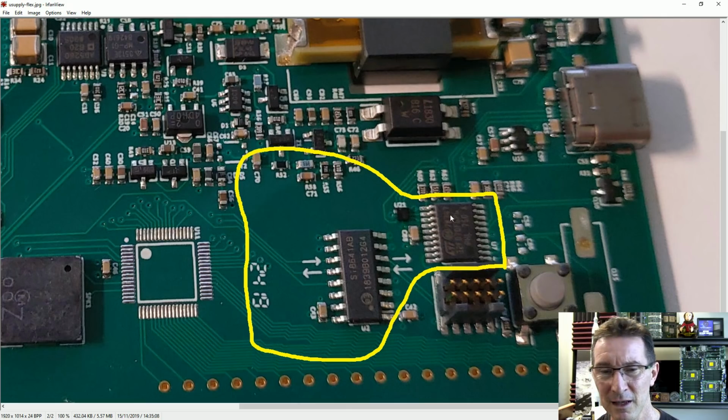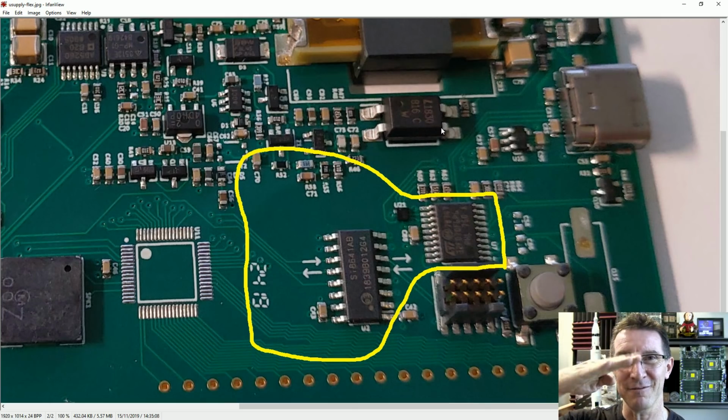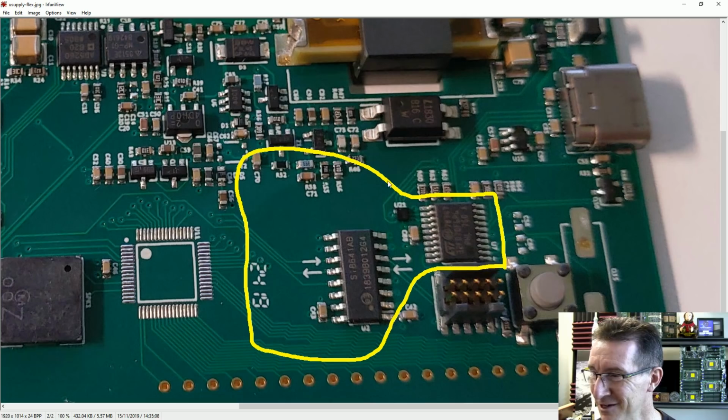So really, yeah, I think I'll just have it coming out like this, because there's a bit more gap between that chip and those pads than there is between these resistors and these pads down here. And as I said, if you put the flex coming up here like this, then it's going to flip up on top of that. That's quite a large, thick package there, so it's really going to flip the chip up like this, and I don't really want that. So I think I'll have it coming out the side like that.